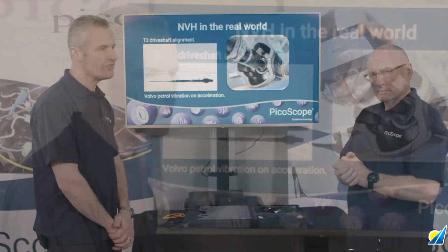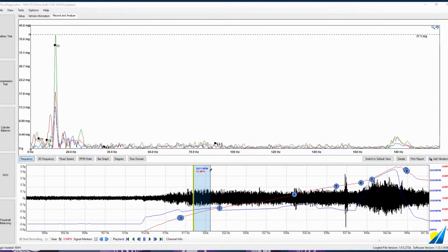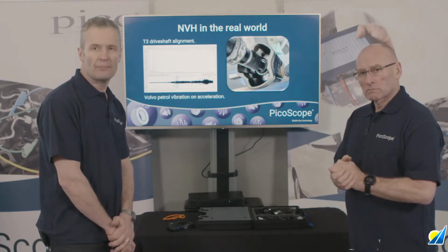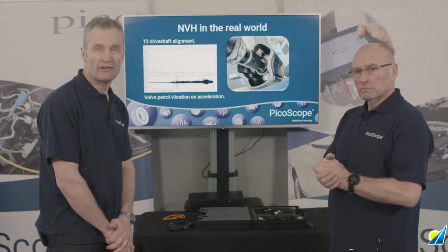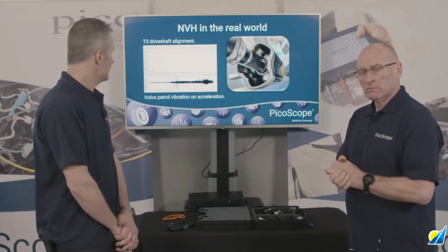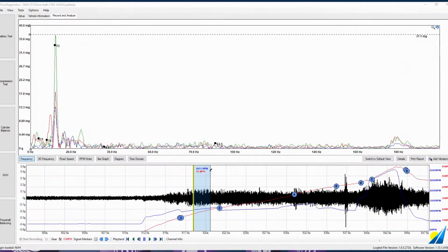So this case study looks at a T3 vibration. You can see from the chart there, T3 lateral vibration, so that's the Z-axis, and this occurred only under acceleration. So let's just clip that all together. We've talked up until now about T being tyre, and that is right. But also it can be other components rotating at tyre frequency. So we're accelerating, T3 almost off the chart, then of course as we level out, take the load off the component here, vibration is reduced.